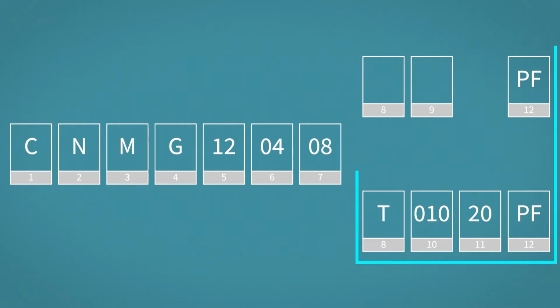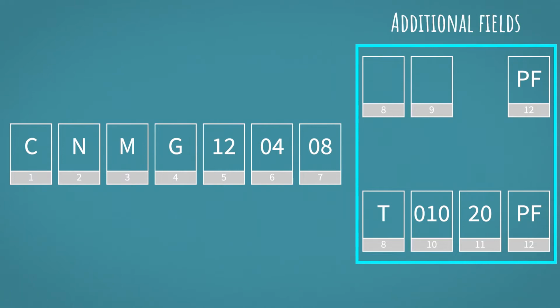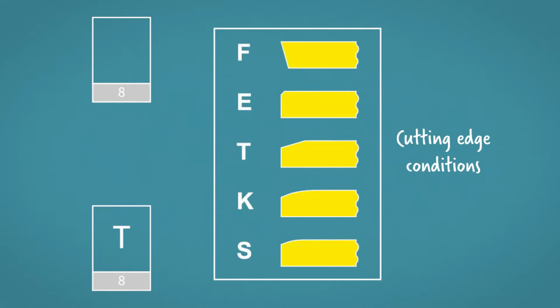With the first 7 parameters, we have concluded the information always present in the ISO coding of the mechanically clamped insert. As we said at the beginning of the lesson, fields 8 to 11 are additional, and typical of geometries related to insert materials other than carbide, such as ceramic or CBN inserts. To be precise, field 8 indicates the condition of the cutting edge and the presence of honing on the cutting edge that increases the cutting edge strength.